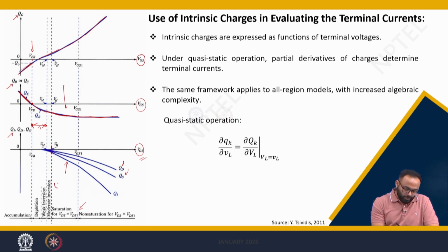So remember, it is square law dependent, that is (VGS minus VT) whole square, assuming that we are not considering short channel effects, velocity saturation, mobility effects, etc. So this is just a quadratic part, and after that it becomes linear, because you know the equation is nothing but mu into W divided by L into COX dash into (VGS minus VT) into VDS minus alpha into VDS square divided by 2. So that is what a slight change is visible, because you are entering from a quadratic part to a linear part.